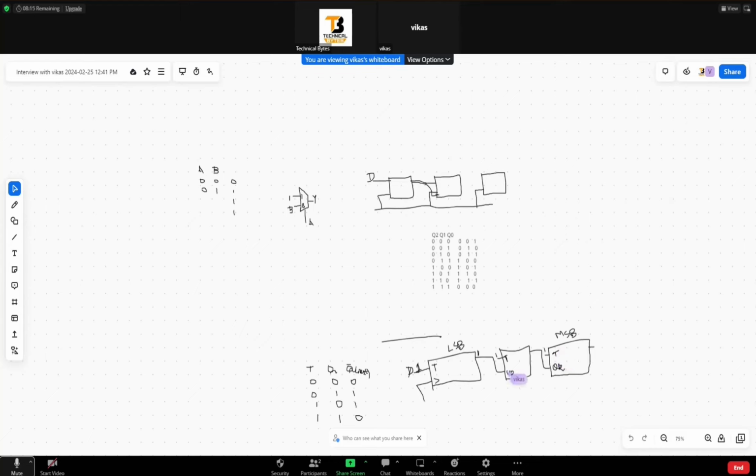So here, when this clock edge is seen, this bit will also change from zero to one, and at that time this one can also toggle. Like that it will be propagating, and each bit will be toggled based on the values being propagated from the previous flip flop.